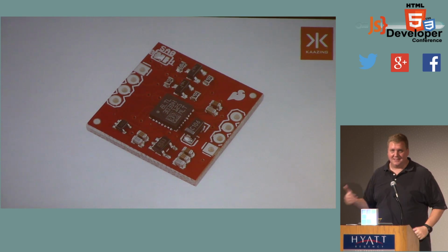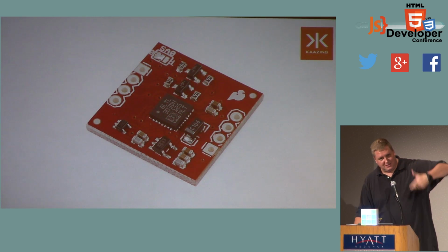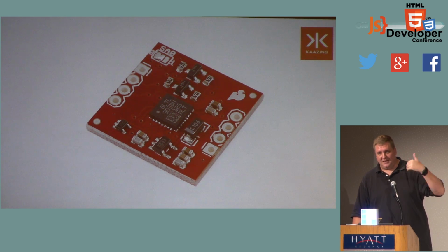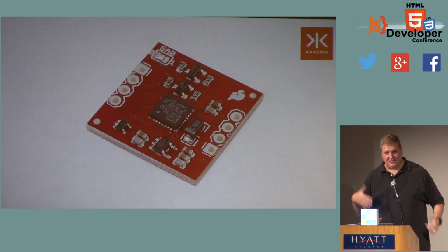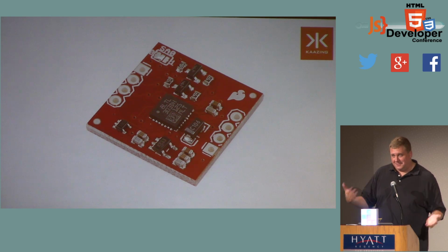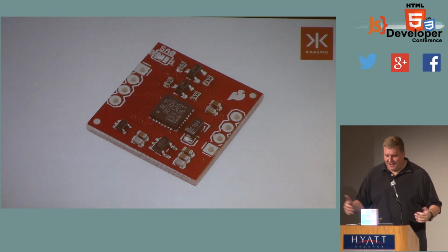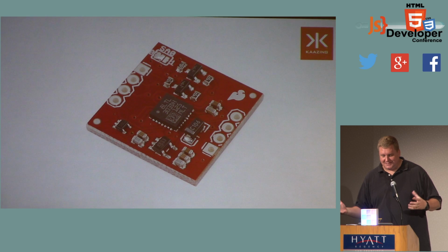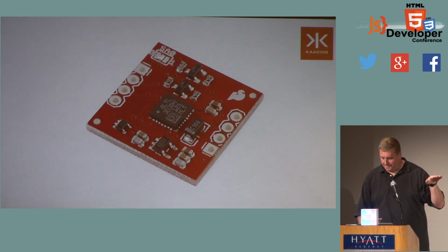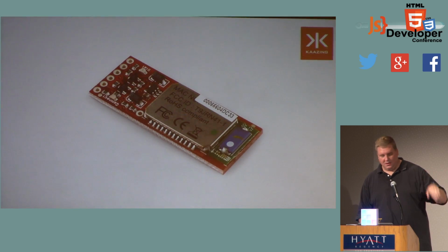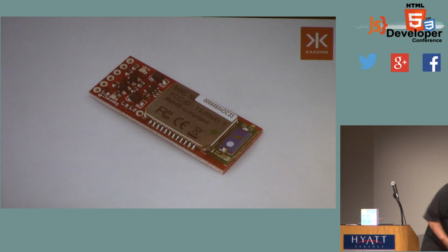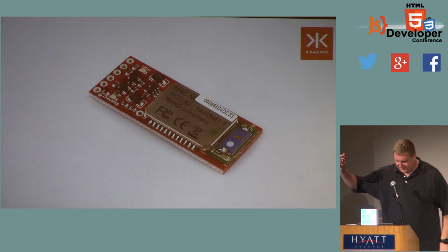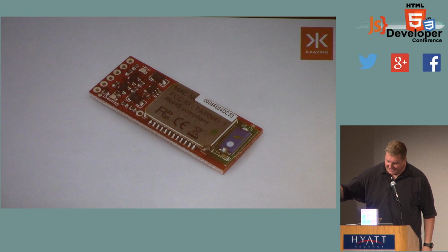So this actually has a magnetometer in it as well, so that you can tilt the chip in any which way, and it knows which way is up and can do the math to calibrate back onto the direction that you're actually pointing. And it also happens to have an accelerometer to help with that math. So I get full tilt access, and I get the compass heading as well. Nice little chip. That I'm going to pair with this guy, which is a Bluetooth module. I soldered both of these onto the board and just slapped them on an Uno here.